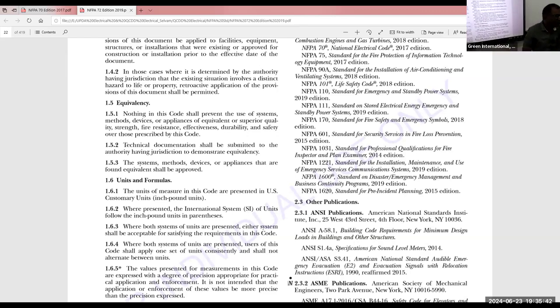Because in the general notes, they mention the emergency light, what is the minimum illumination level. They mention the manual call point, what is the height of the manual call point. They mention the smoke detector, what is the distance in the corner, and the distance between two smoke detectors is different. They mention from the wall to the first smoke detector, what is the distance. So most of the details you find in the general notes. But it depends on the project. Based on the drawings, they may have at least 2 or 3 different project drawings. You refer to that, you will get the details.